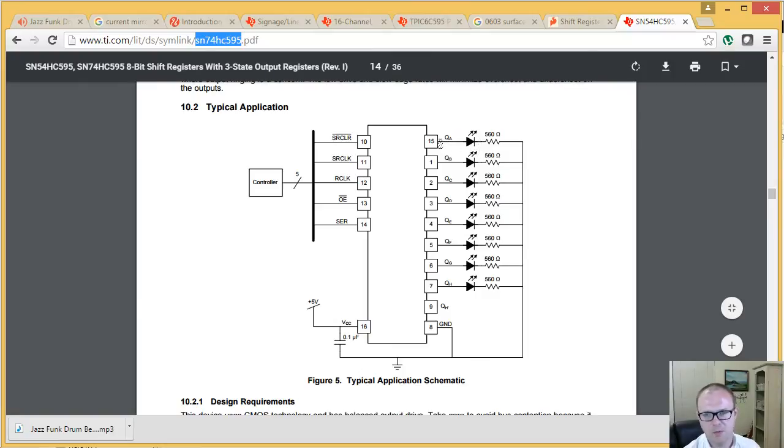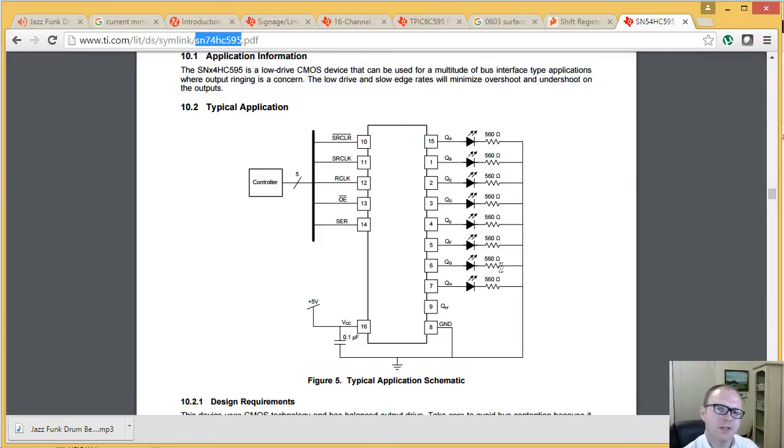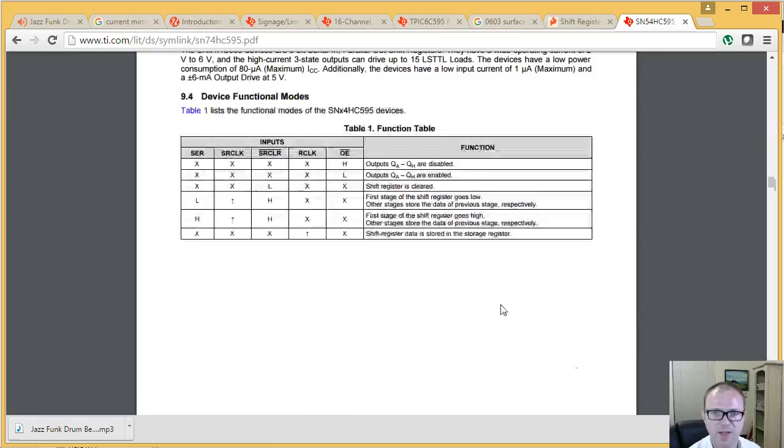And then the example schematic here is a bunch of LEDs and the appropriate current limiting resistor, and that's pretty easy to use. The challenge there is that red is going to require one value of resistor, orange is going to require another, and green is going to require a different one again. That becomes a bit of a pain to manage, and so we can use things like current mirrors and so on to manage that a little easier. And given the price of some of these transistors and so on, it's not something that adds a significant amount of cost.